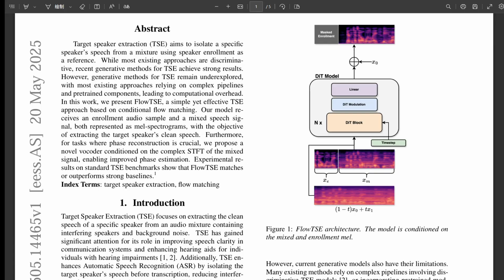The phase information. Why does losing that matter so much? It's a really good question. For a lot of things, like just basic speech recognition, maybe it's okay. Standard vocoders can often estimate phase reasonably well. But not always. Not for everything. If you need really precise timing, or if the output needs to feed into another system that works directly on the audio waveform, like say HuBERT, then phase becomes critical. Or for really high fidelity uses, think professional audio or advanced hearing aids doing complex spatial processing. Without accurate phase, the waveform might sound okay spectrally, but have subtle timing issues or artifacts.